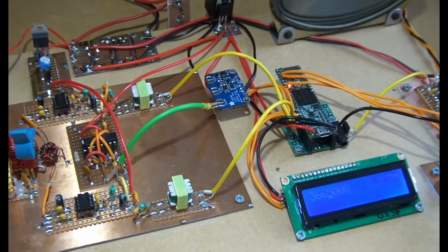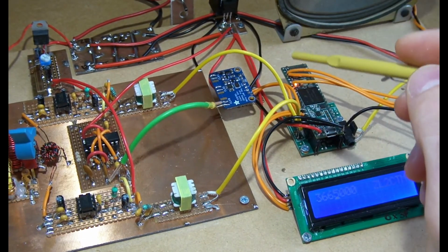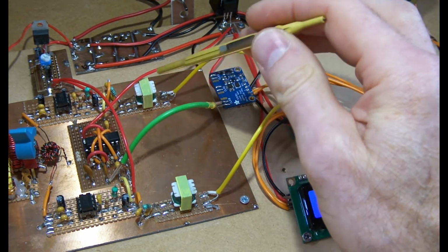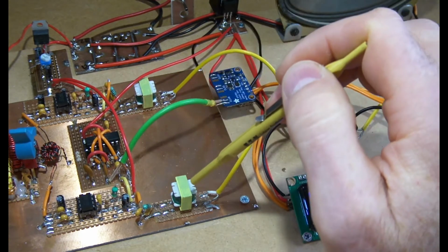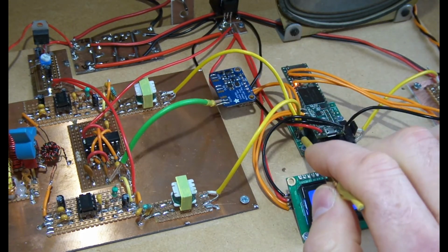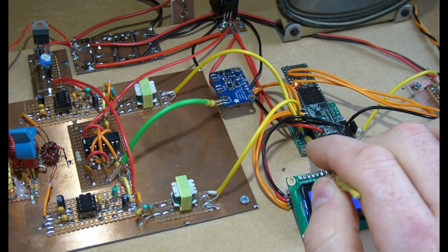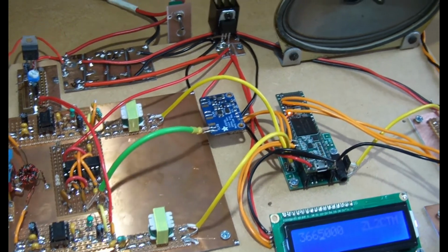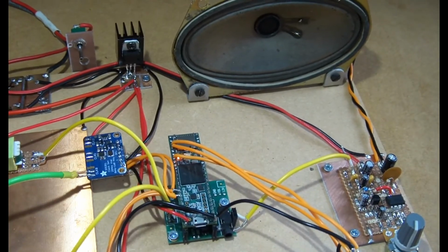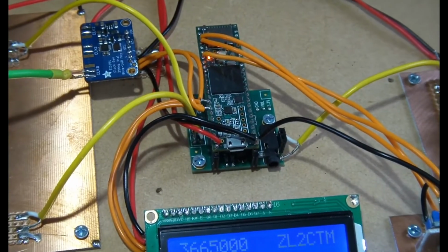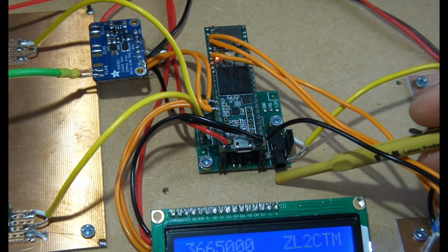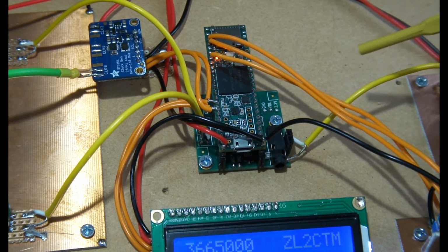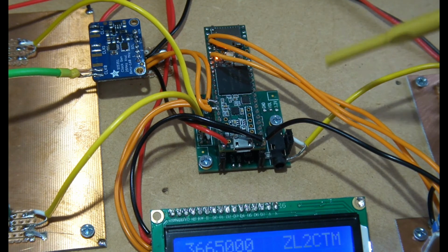So we've now removed that big black wire we talked about last time, and it's got some little audio cables here taking the audio out from both the I and the Q channel and feeding that down into the line in on the audio shield. On the other side, I haven't bothered to use a 3.5mm audio connector here, and I've just tapped directly into the pins there.